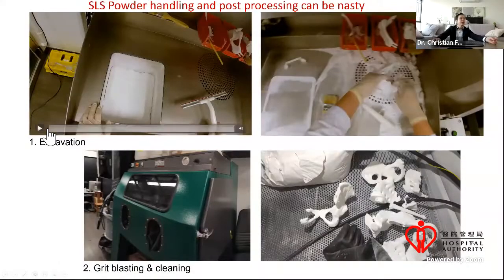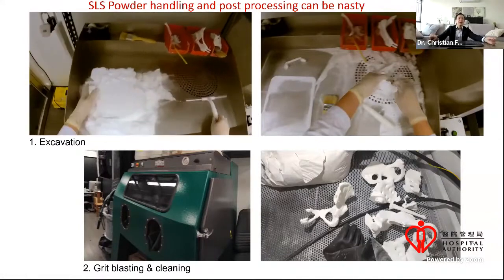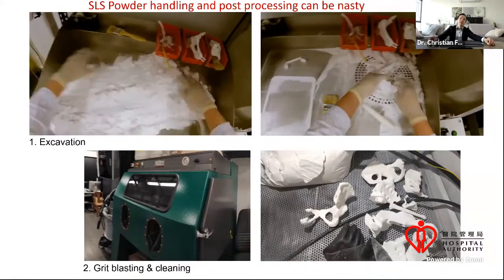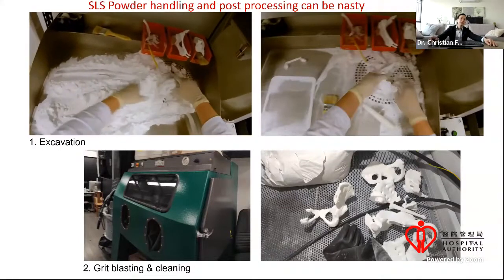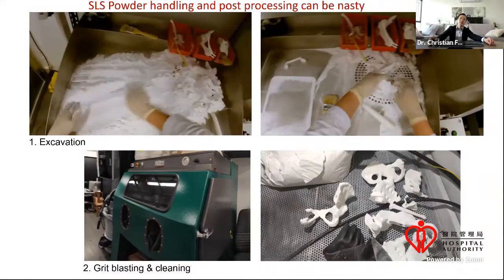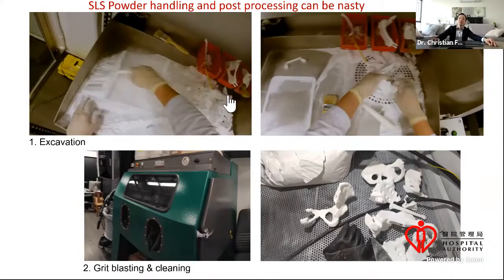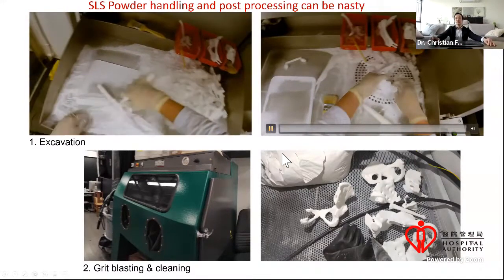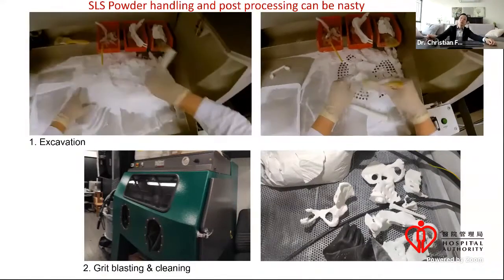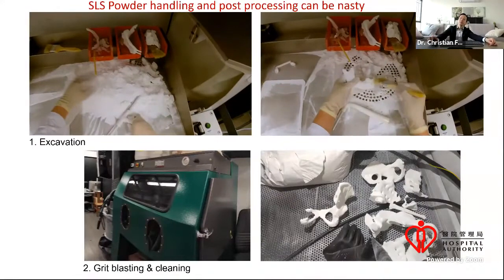The problem of the SLS, the selective laser sintering, is that after it prints, you see it comes out like a batch of powder, and then you have to manually excavate. It's like archaeologists excavating the parts from soil, and then it can get quite messy here. Actually, we use a brush to remove all the fine particles of nylon dust. And this is also an occupational hazard.